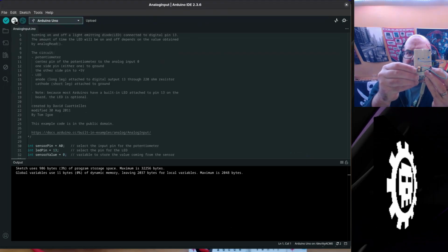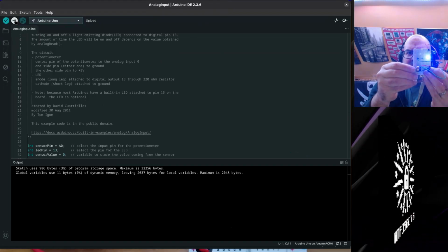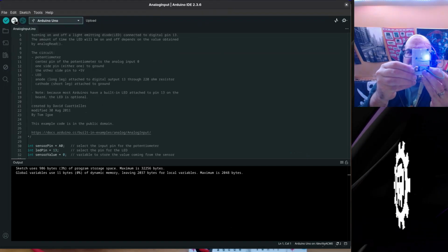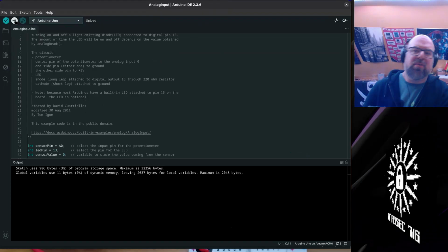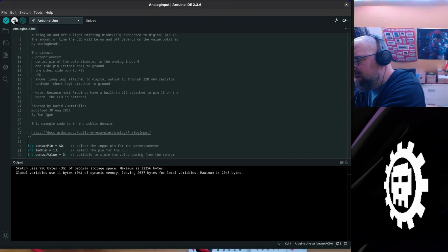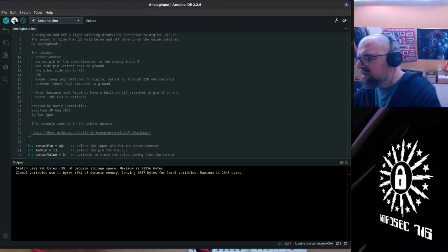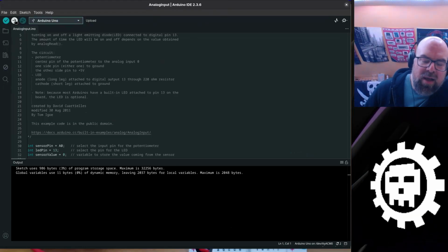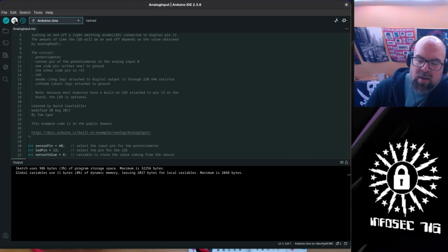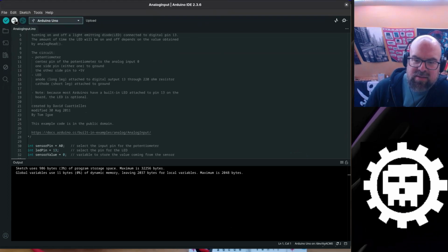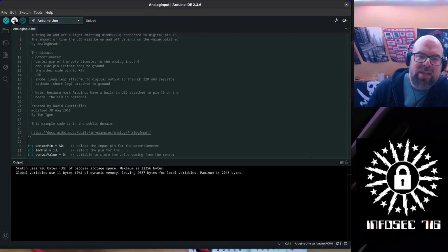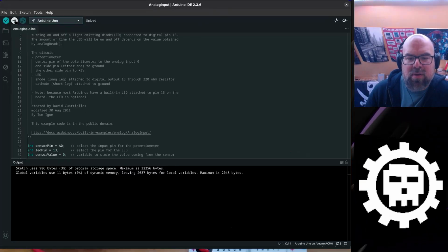So this analog input allows us to have a sliding scale of values that we're feeding into our circuit, and then programmatically we can act on those inside the Arduino environment, right? We can use this to set all kinds of stuff. If we wanted to build a circuit that strobes the lights faster when the ambient light goes down, we could do that with a photoresistor.